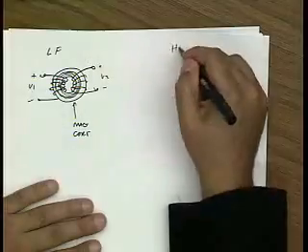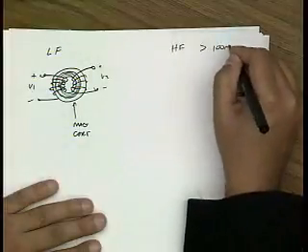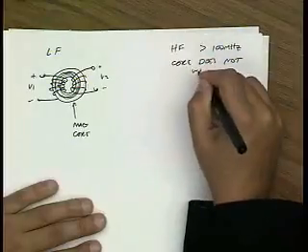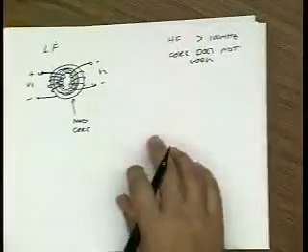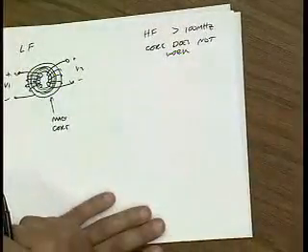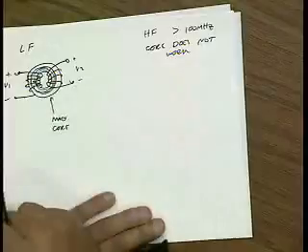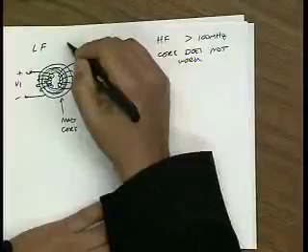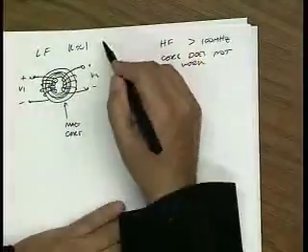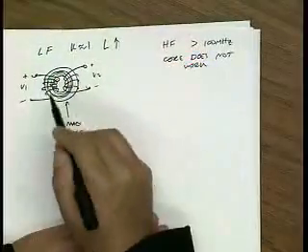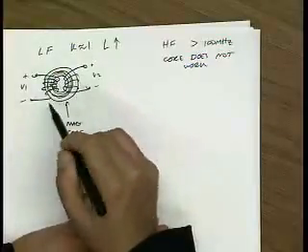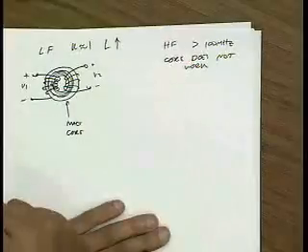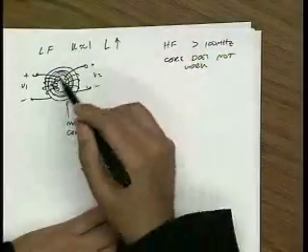Unfortunately, at high frequencies, let's say above 100 megahertz, the core doesn't work. So it's very hard to find magnetic materials that work at high frequencies. So at high frequencies, this core is essentially not there. So if I build a transformer like this, here at low frequencies, K is roughly 1, and L is huge because of the core. The L is boosted basically by the magnetic permeability, mu.